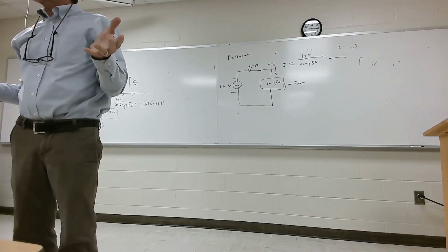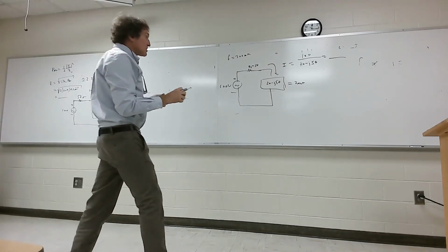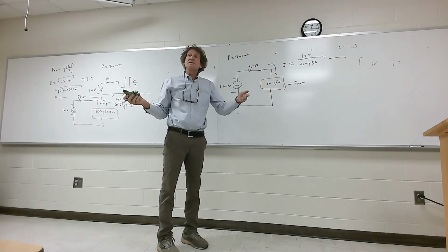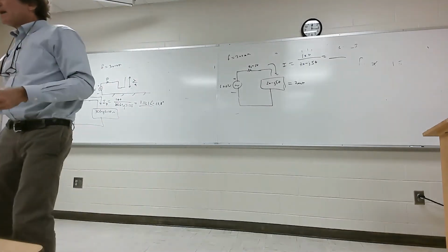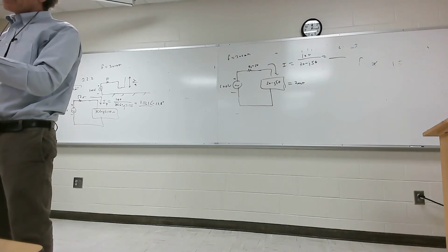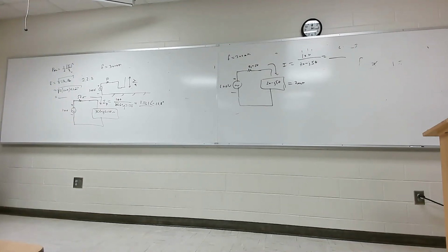Y'all follow me on how to do this? But we don't add the 50 for the quarter wave? Well, look, here's what I did. See, the 20 and 50 is 70, right? He's replacing that quarter wave monopole with this lambda over 5 monopole, isn't that right? I was just wondering, since on a quarter wave, we divided by 36. No, we took the half wave impedance and divided it by 2. Right? The half wave, this is given, the impedance of the monopole is given. It says directly, this is it, use it. He says it's 20 minus J50, right? Alright, that's it. You don't have to do anything else with that.